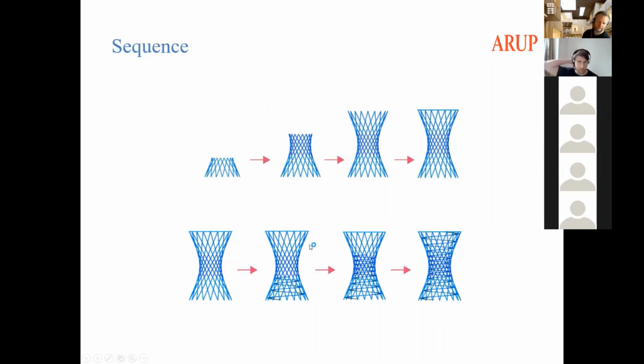So I just want to talk a little bit about the sequence. And again, I think Levi has some really nice on-site photos to describe this better, but this is just to say how this influenced our design. So the diagrid columns were erected in parts of 3 with temporary supports. And then as soon as we had the platform ring in place, we removed all the temporary supports and started erecting these prefabricated sections of the ramp ring between the offset connections. So by removing offset connections, we also reduced the number of prefabricated ramp ring elements.